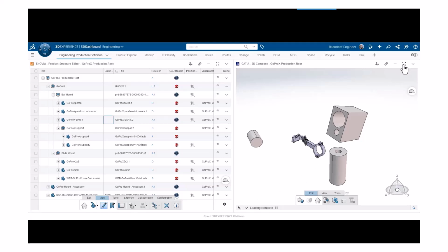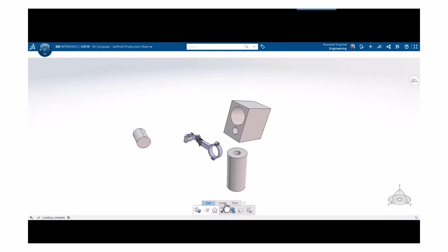So here we go. First of all, I'm going to go ahead and maximize this. If I go to the edit, we'll notice that there is this button called Manipulate. If I select Manipulate, it gives me a set of, they're not really connections or constraints, but they're meant to be something like that. And they're cumulative, so if I select multiples, it allows you to be cumulative in your different selections. Right now, I'm just going to select Product. And I'm going to take this object and slide it over here. And you're going to notice it tries to position itself into here.